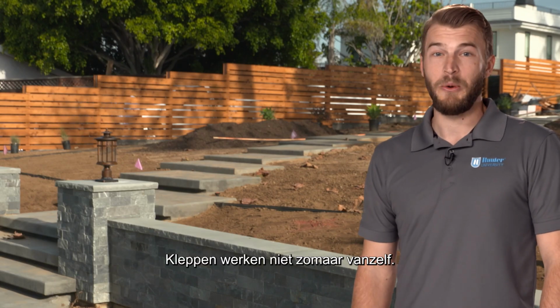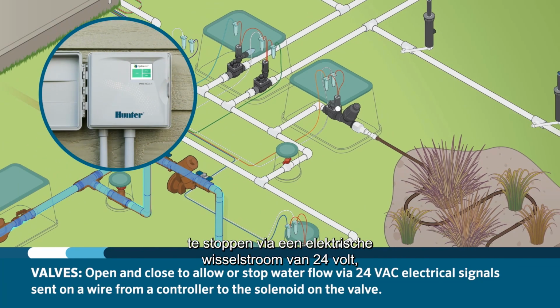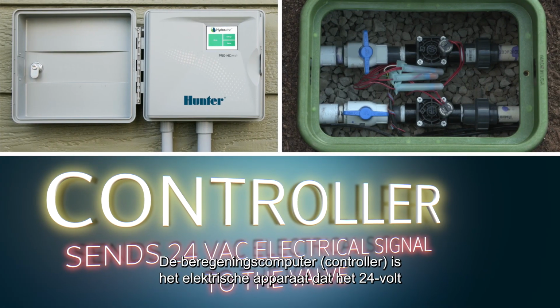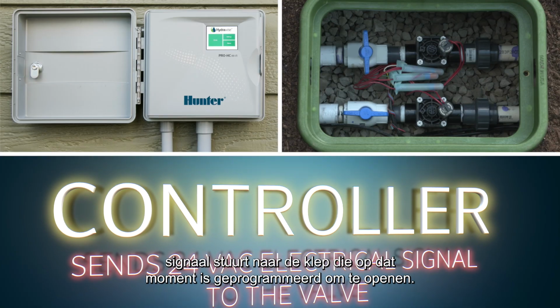Valves don't just operate on their own. They open and close to allow or stop water flow via a 24-volt alternating current electrical signal sent on a wire from a controller to the solenoid on the valve. The controller is the electrical device that sends the 24-volt signal to the valve that is programmed to open.